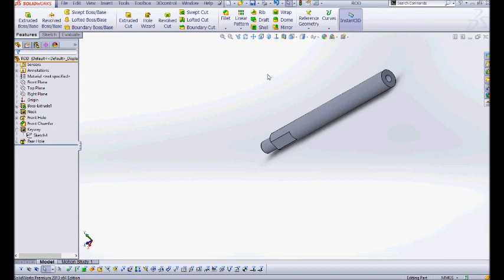Now we have to get the youngest child. That's going to be the keyway. So we're going to come back and bring the bar down for the keyway, and this time it's giving me this little yellow exclamation point. Do you see that? And notice that my keyway is really short now because the keyway sketch is over here.